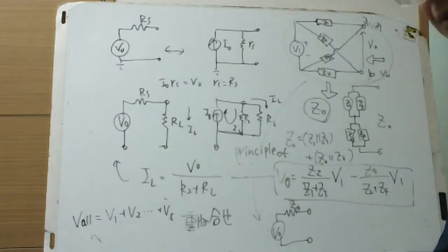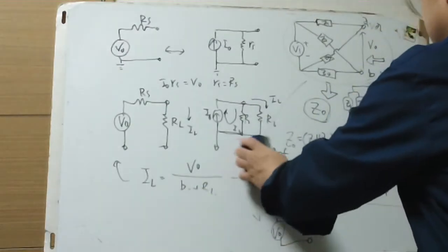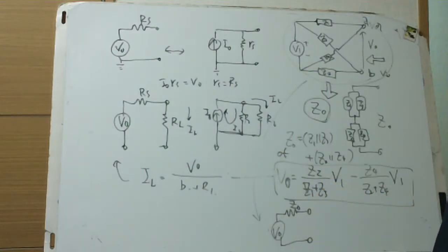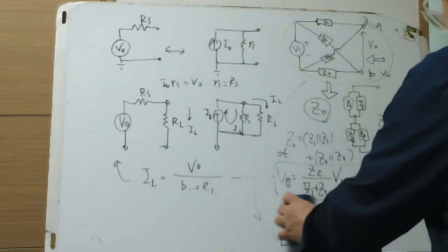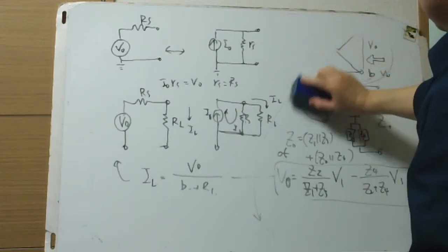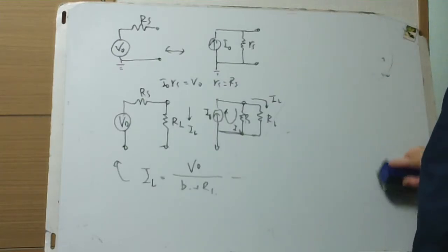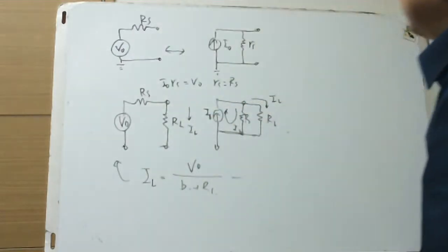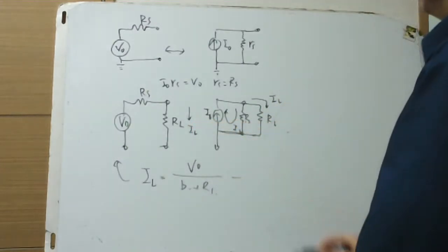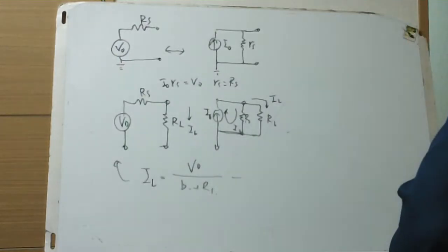But anyway, on the second step, we need to calculate the open voltage, and the open voltage in series with the impedance from the first step makes the Thevenin equivalence of any circuit. Deriving the Thevenin equivalent accurately in any case, for the start, the simplest loading case is looking at this.